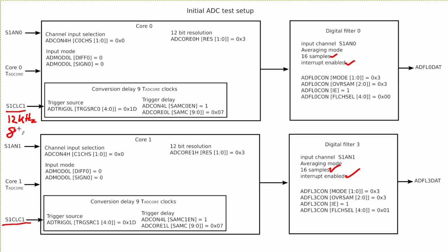And now a bit of math comes into play, as I have to figure out what kind of ADC clocks I need to get 16 conversions complete in less than about 81 microseconds, or about 5 microseconds a conversion. From the datasheet, conversion time for a 12-bit result takes 8 T-core SRC clocks and 14.5 TAD core clocks.